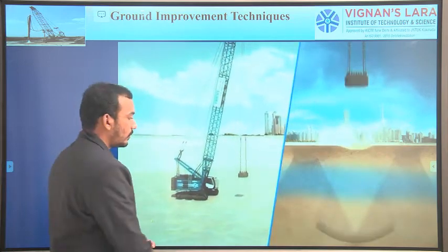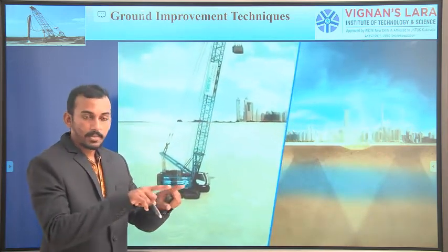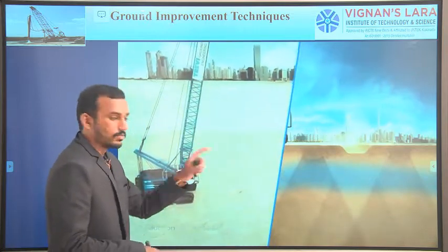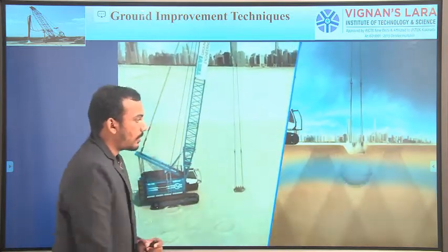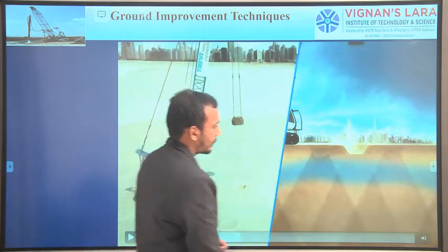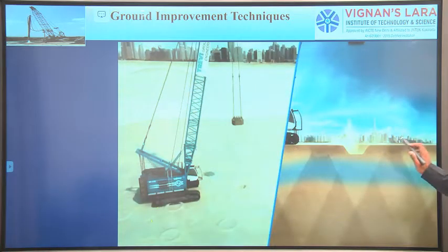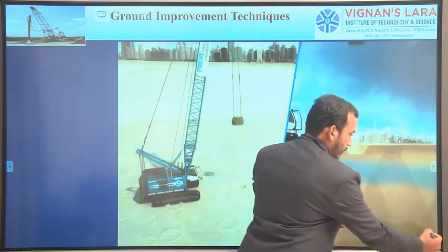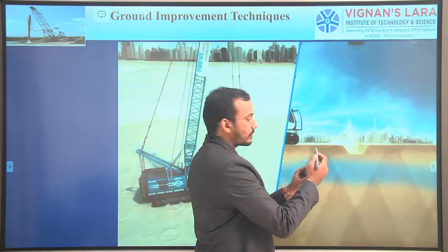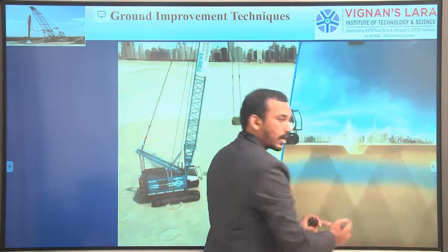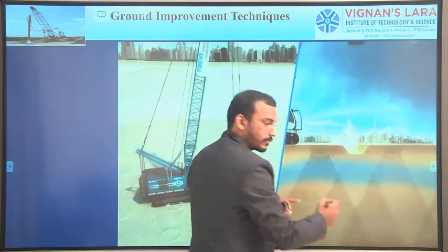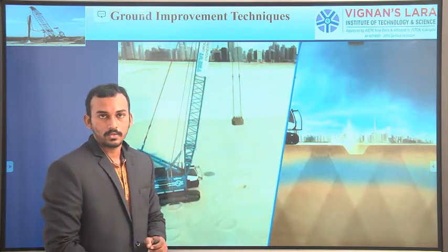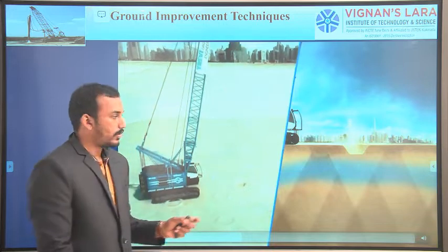First of all, we completed the compaction of the square areas. Now we are giving circular areas in between the square areas. Again, do compaction work. Due to the first compaction, this trapezoidal area is compacted. Then we move to the next position, and this trapezoidal area is compacted. Then move to the next position. Likewise, we need to compact the entire soil. So watch the video.